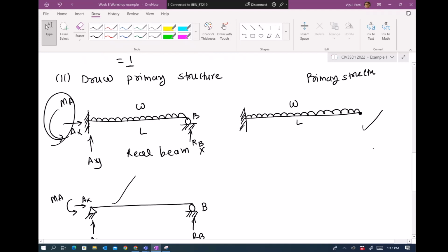Now, you need to think, what is equilibrium? Equilibrium is basically saying that the structure should stay in its position. So if this book is in equilibrium, what does it mean? That it has gravitational force, and all the forces coming on that beam sum to 0. It is not rotating, meaning that all the moments in any direction are 0. Equilibrium equations can be made more than 6. There is no problem: if you create another diagonal axis and take moments about that one, it should be in equilibrium on that axis as well. But to keep it simple, here we just work in a Cartesian coordinate system, or whatever coordinate system, along the principal axes x, y, and z, and so on. So what is equilibrium? Structures should stay in their positions, because we are not working with space structures like satellites and so on.